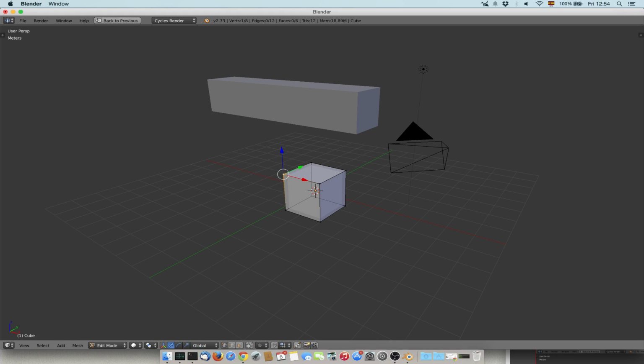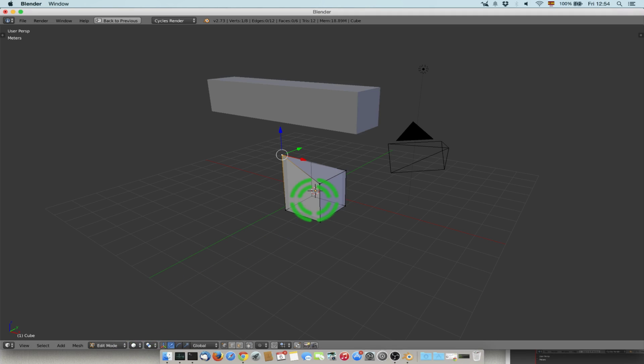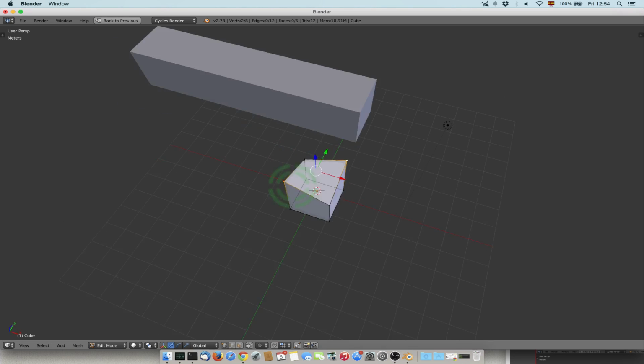I can move the specific vertex. I can even do, you know, grab Z 1, and it's precise. Okay, or I grab Z -1, and it's down there. So in this way, you're very precise about the transformation that you want to do. You can select more vertices, so in this case, grab Z 1, and of course, this is what you get.